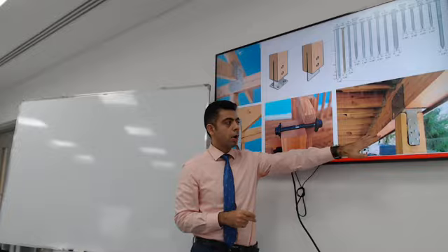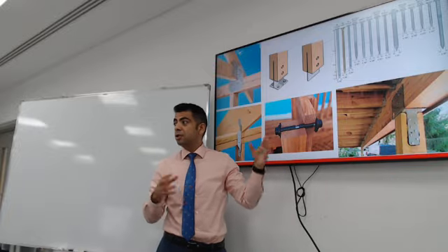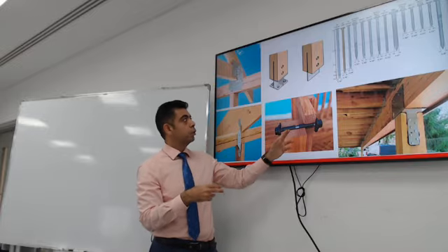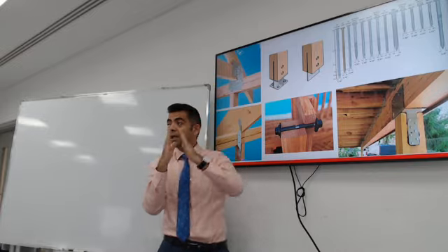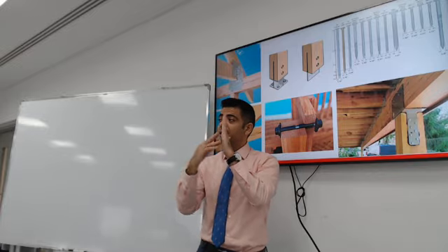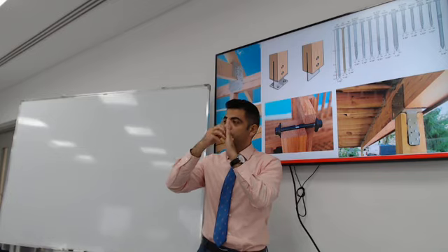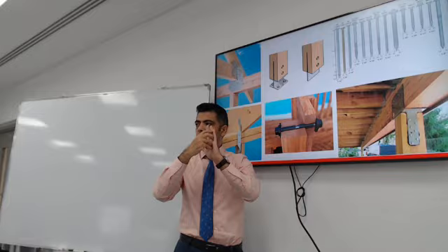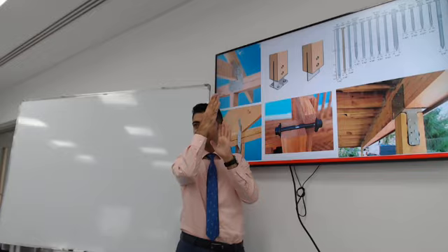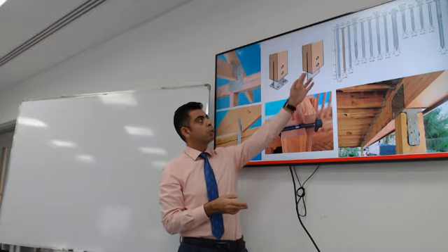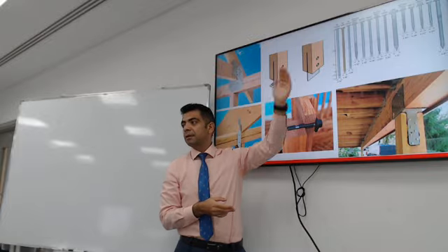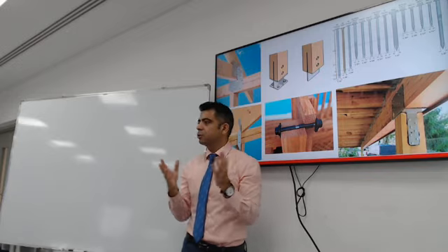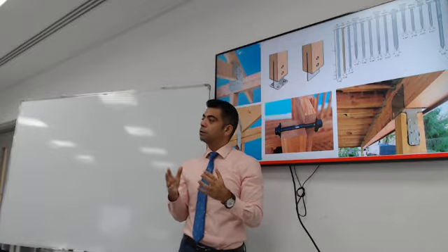And there are more robust connections. You can have bolts to connect wood. You can have steel plates sunk in the wood piece and use bolts with it. You can have a detail called a countersunk bolt, where the bolt is sunk in the face of the wood piece, so it's not sticking out. There is actually no limit to how fancy the finish or the look you want to get. You can create very beautiful buildings.